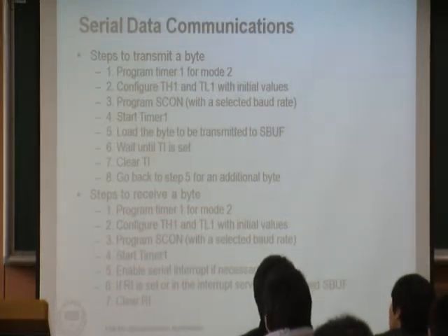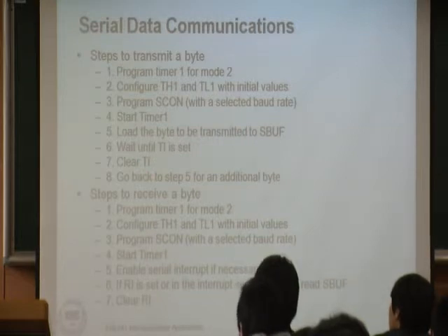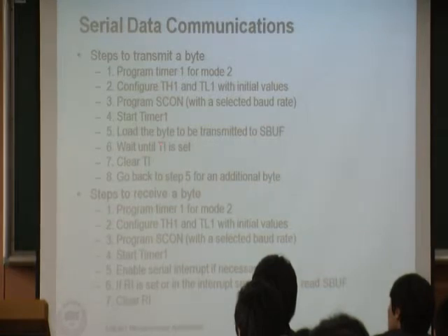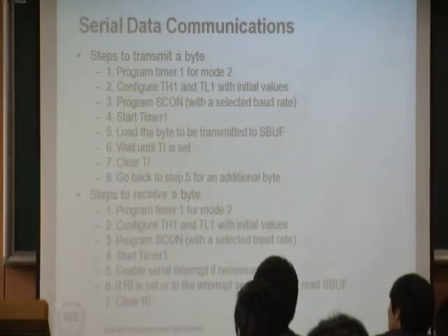If you want to transmit some byte, then now it's time to write this value into SBUF. That's all you need. Writing the value into SBUF, then hardware will transmit. So you are basically watching the TI until the TI bit becomes 1. When TI becomes 1, that means it's time to write the next letter. So you clear the TI first and go back to 5 and keep doing it.